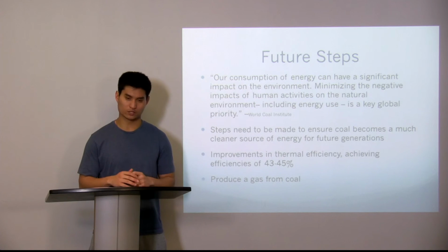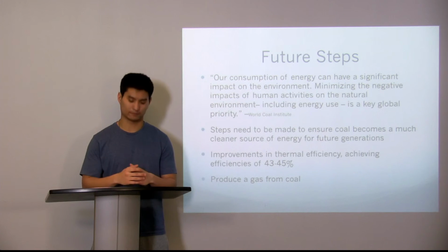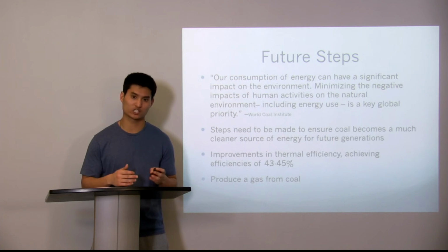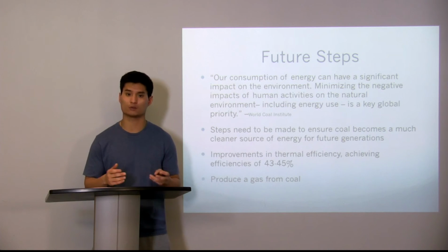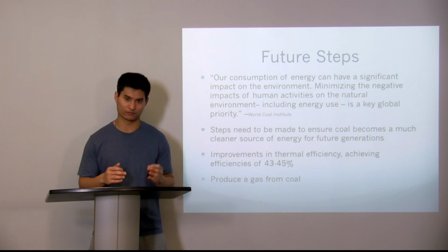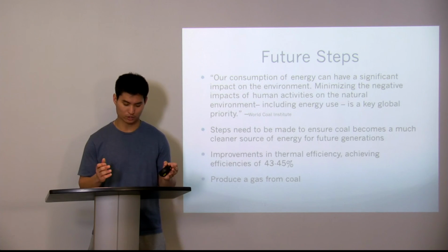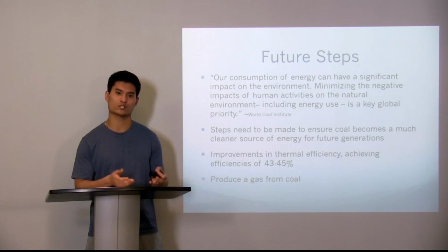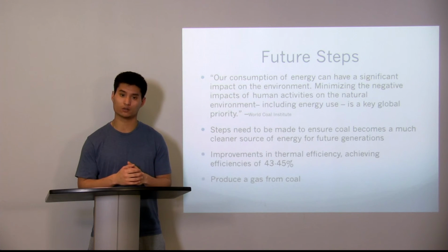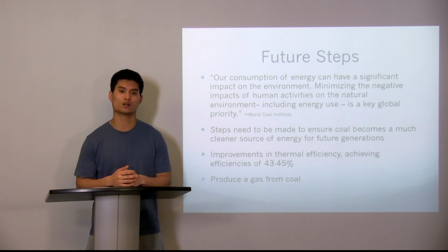An important step in reducing carbon dioxide emissions in coal power plants is to increase the thermal efficiency of the plant. Thermal efficiency is a measure of fuel conversion efficiency for electricity generation process, an essential process in burning coal. According to worldcoal.org, the global average of thermal efficiencies in coal power plants is around 30%. New technology is forming that allows an overall thermal efficiency upwards to 45%. This technology operates at supercritical, meaning they operate at much higher temperatures and pressures than conventional coal power plants.